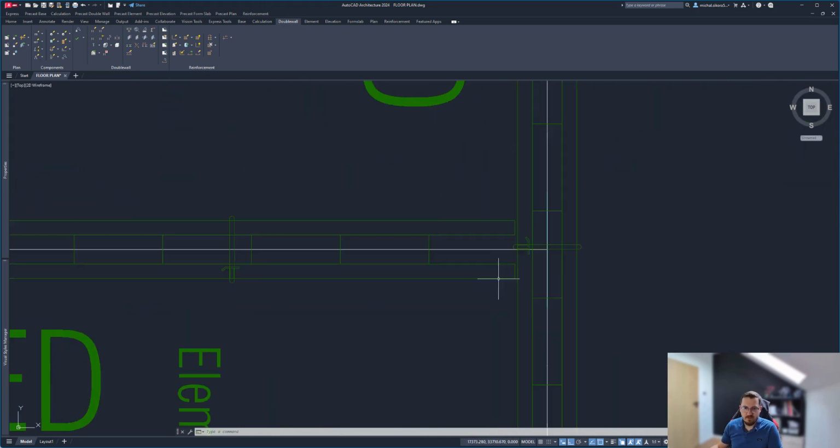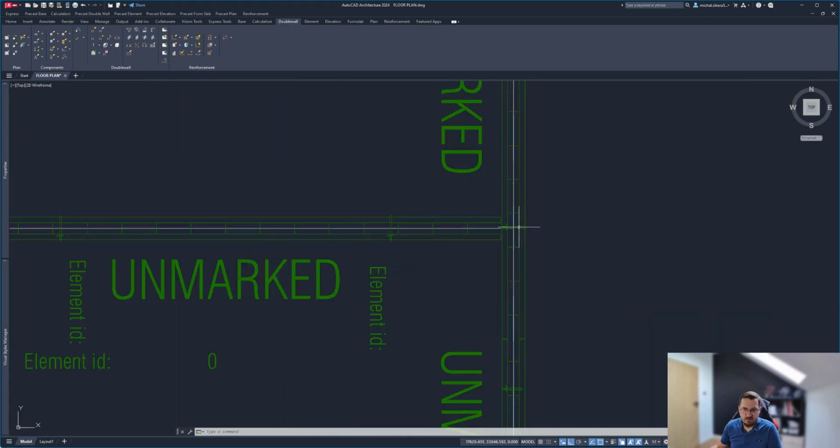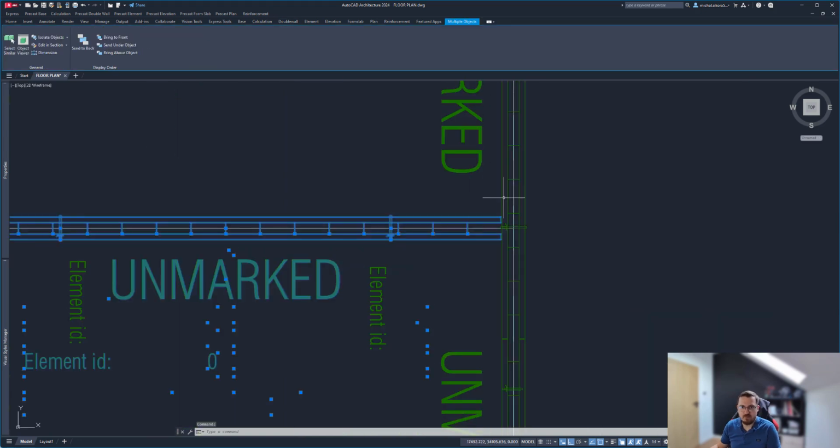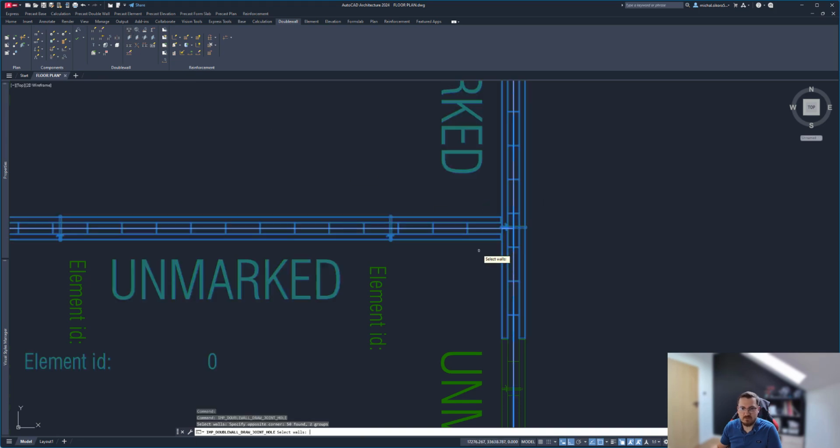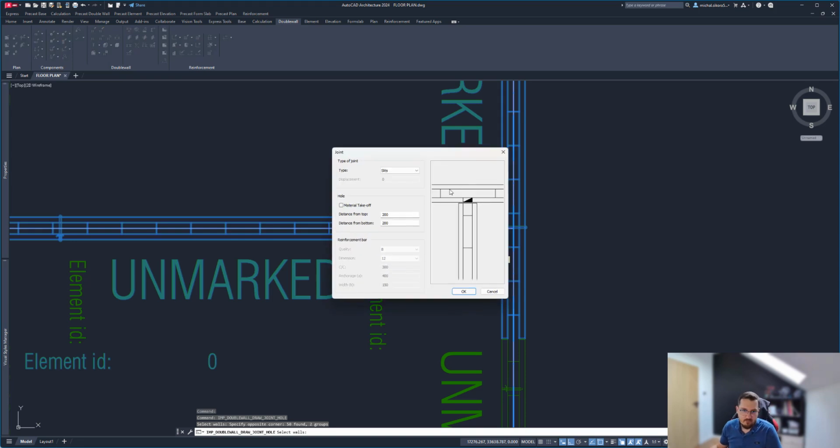Okay, with that, let me go ahead and, for example, create a connection between this wall and this wall, because this requires a T connection between those. So let's tool for that. Let me select those two walls, like so. And I have a bunch of options here. So it automatically detects that we have a T connection between double walls, and we can either create a slit, we can create an open hole throughout both panels, or we can add a U-bar and a slit for different type of concreting, different type of connection.